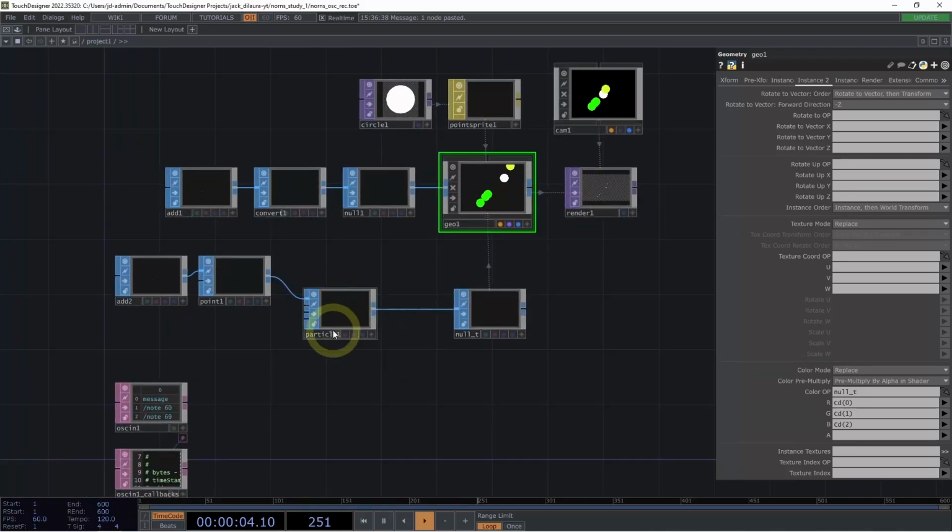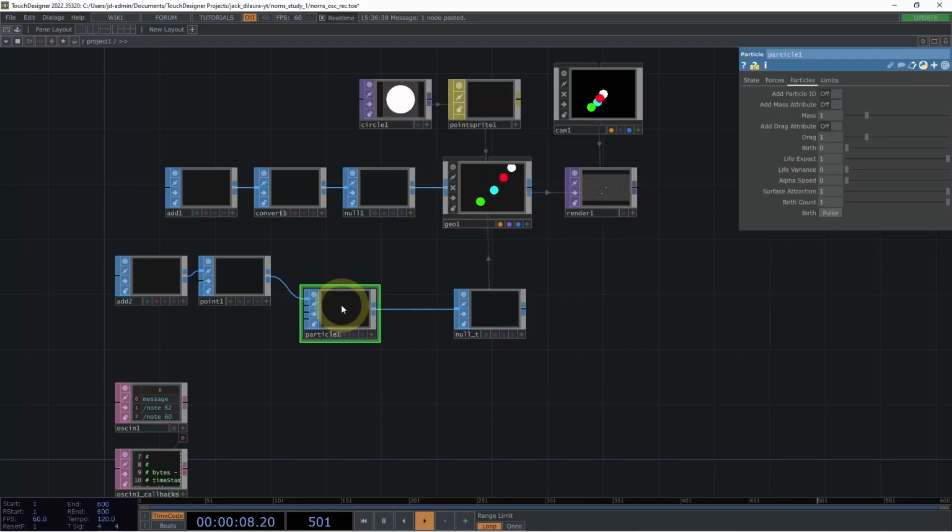So what I did to add a little bit more interest to this particle system was to, first of all, set up a little bit of turbulence on the forces page. So simply by increasing the turbulence values here to 1, which I'm going to do via the value ladder. So I'm going to middle mouse click on turbulence, move while still holding the middle mouse button down.